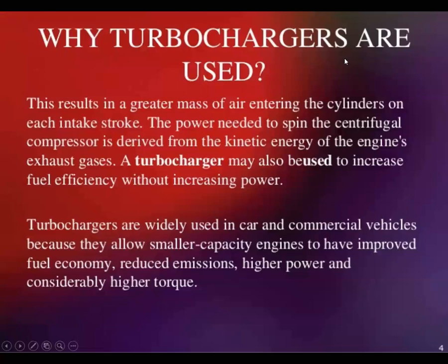So why are turbochargers used here? It is a basic, important question. Turbochargers are used so that a greater mass of air enters the cylinders on each intake stroke. Every suction stroke, the air is entering. The power needed to spin the centrifugal compressor is derived from the kinetic energy of the engine's exhaust gases.